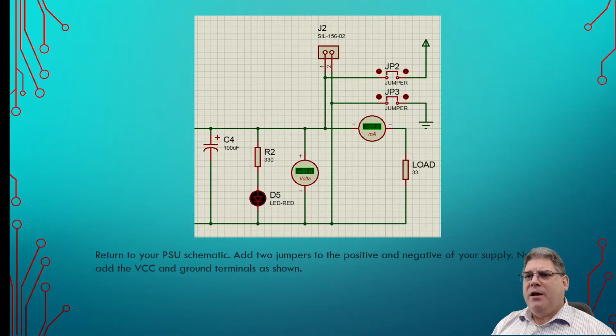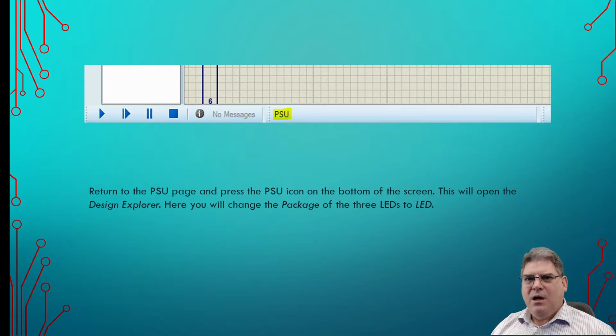circuit. And especially when you're first getting started, or you have a questionable power supply, you might want to put in one of these jumpers so that you can power it up, make sure that your power is good, and then power the rest of the circuit. It also means that you could remove these jumpers and apply a different voltage, which is very useful for things like a development board.